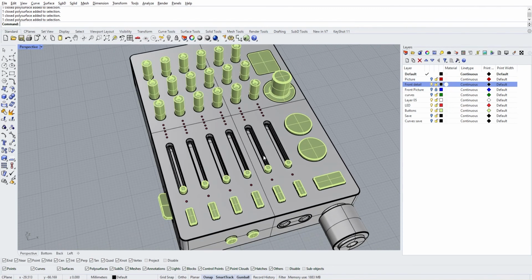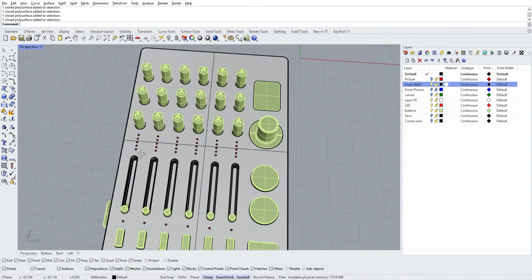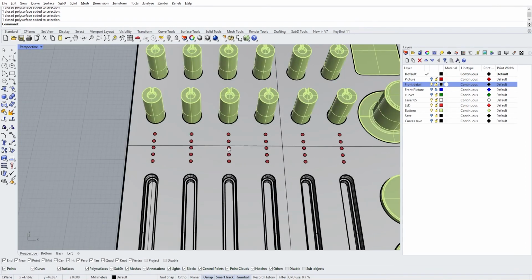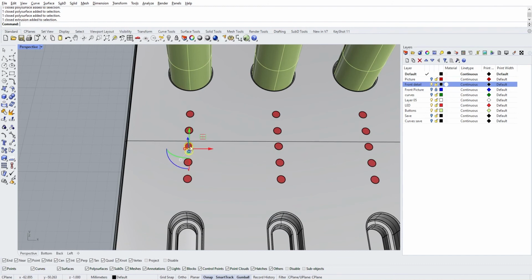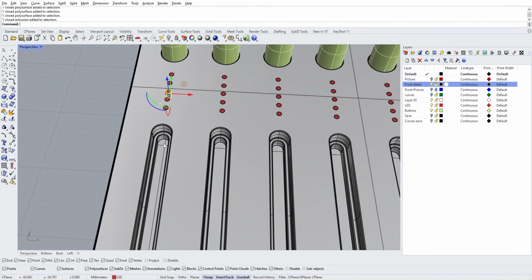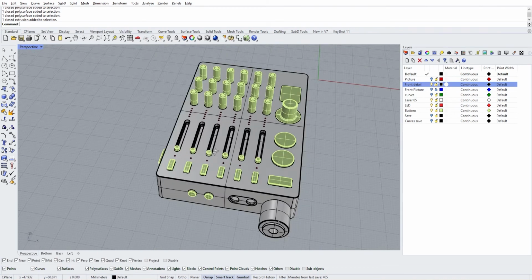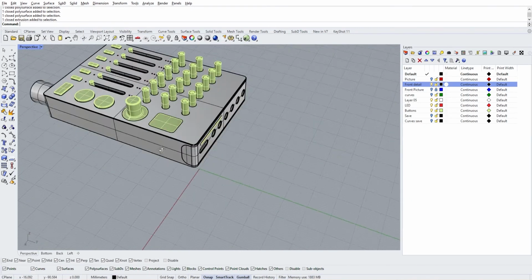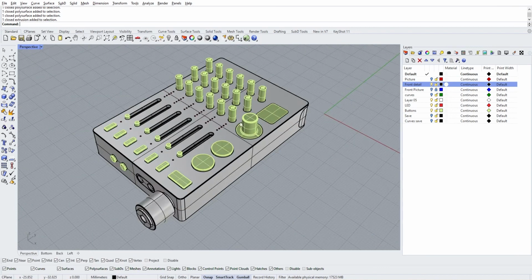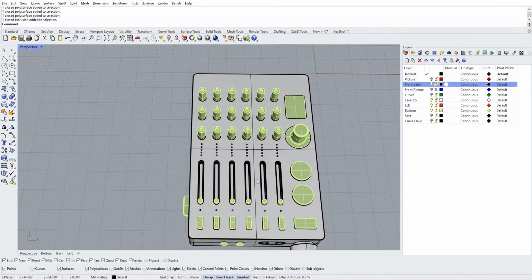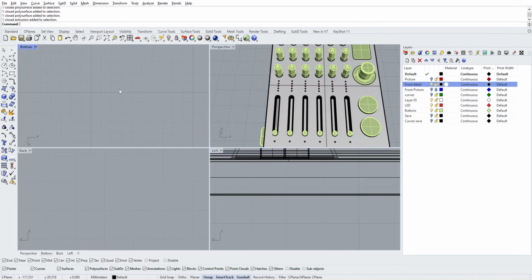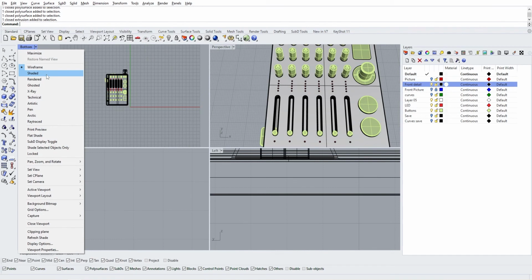So we're going to solve this problem by first isolating those LEDs from under, so that if this is an emissive material, it's not going to emit also inside. And also maybe we want to close the big holes, such as this one, those ones here, and those ones there, and also the back of here. So to do this, we are going to create boxes inside that we will join to the main body.